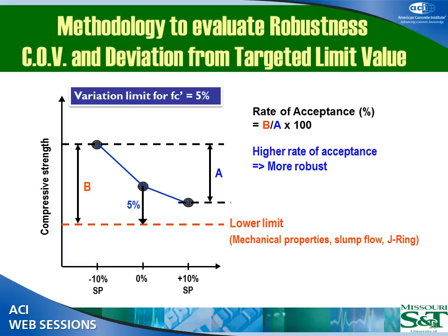compared to what we designed the mix for. This is our mix, intended mix. So what would be the maximum variation from a minimum limit? So if we say, for example, at 7 days, I'd like to have 30 megapascal, so this would be 33 megapascal, or 32 megapascal, this would be 5% from the minimum. So we had minimum for all mechanical properties.